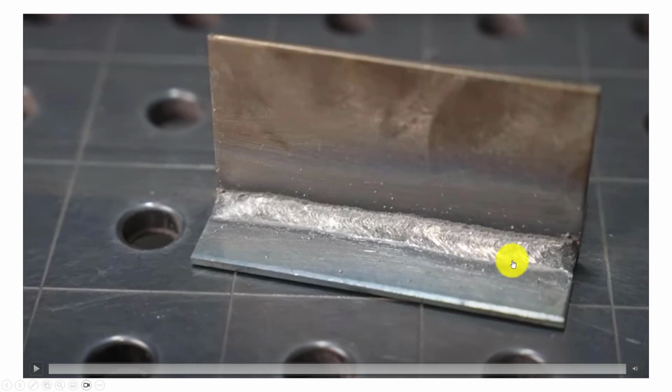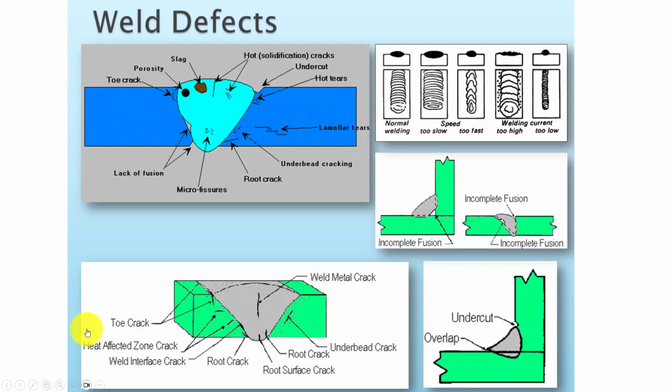Okay. Now the next one we're going to watch, and that's just that same one there. I probably need to hit, there we go. Let me get back to the beginning here of this one. Let's watch this weld. This is going to be a more consistent and better weld going across here. And see how the heat is tying in to the tops and bottoms, and you can see it cooling off, the slag off here. And this is going to make a lot nicer weld on this part. And so we would go in there and then test that weld.